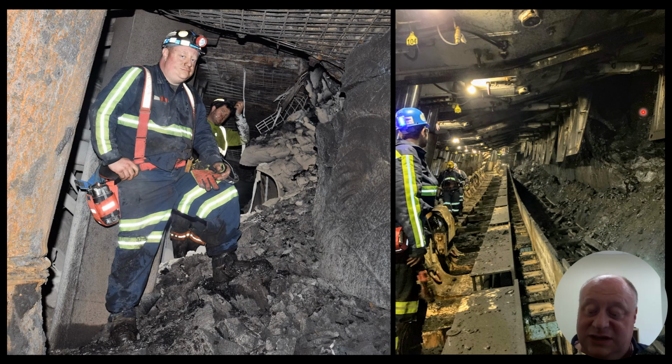So this mine dips pretty decently. It's about 10 degrees or so. It was about 12 feet thick, as you can see. Massive shields in this mine, 2,000 ton capacity. ZMJ. So these are Chinese shields, and they've got the front flippers because this is burst prone ground. So in case you have any burst from the face, that's helping out with that.